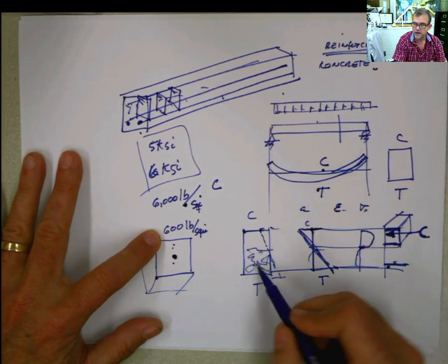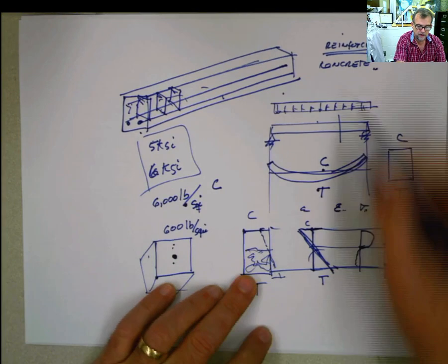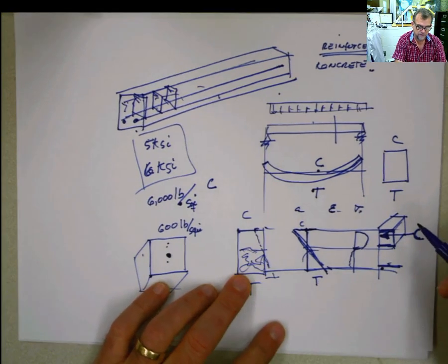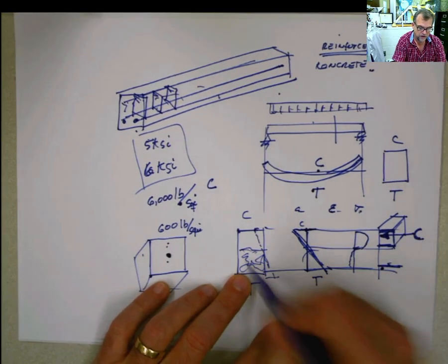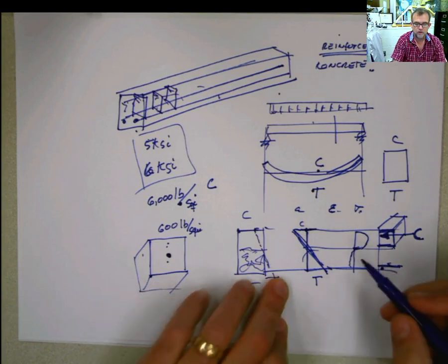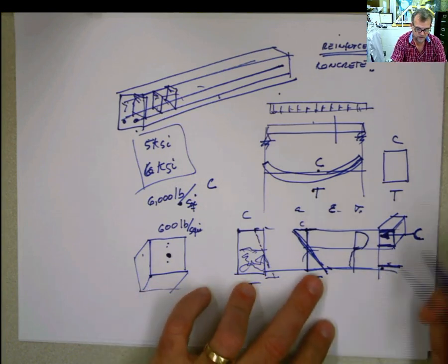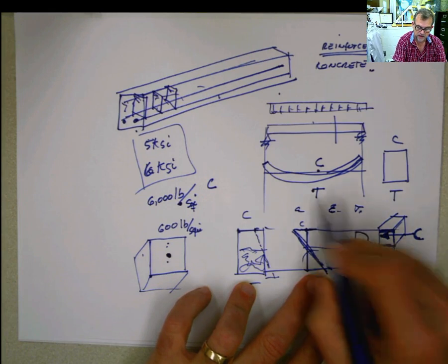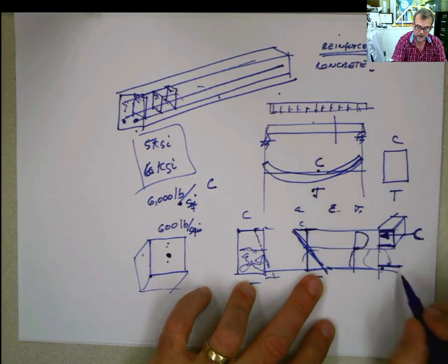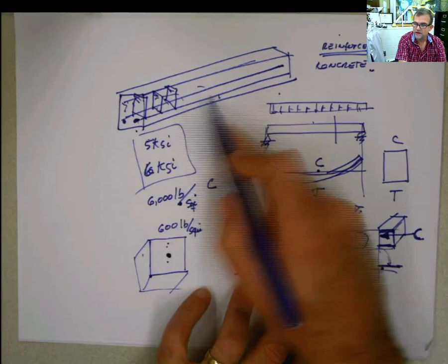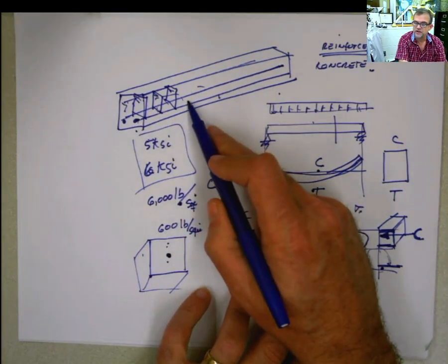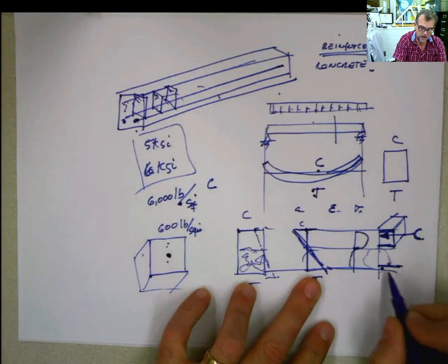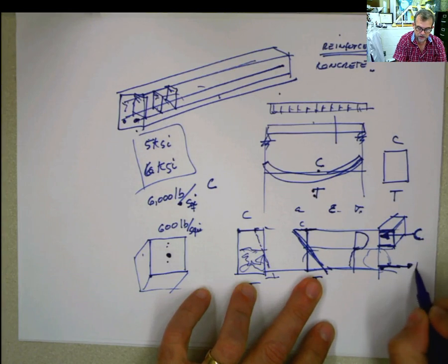And what the theory in reinforced concrete applies is that if the concrete is cracked, it's not working, or well, it's partially working, but this is statics. I don't want to overcomplicate it. So the concrete is not going to be able to resist that tensile force that is coming from here, and that's why you have the rebars of steel, because the steel is really good at resisting tension and is providing this tension in this part.